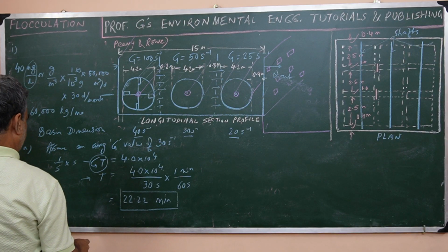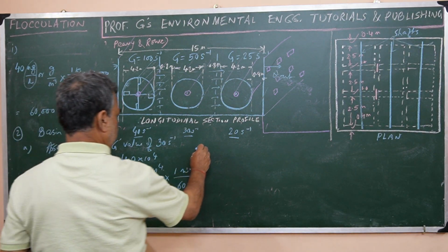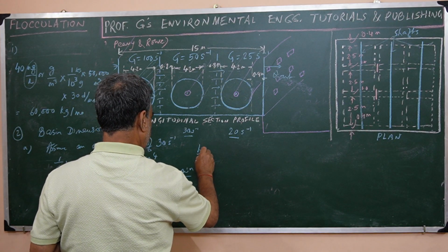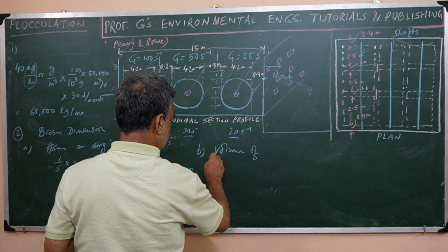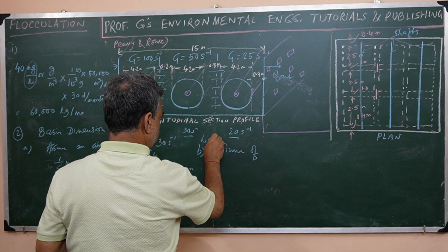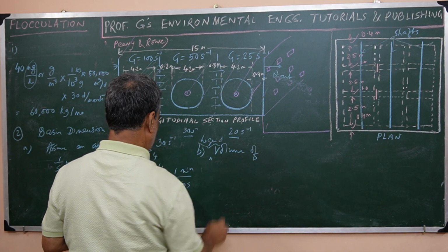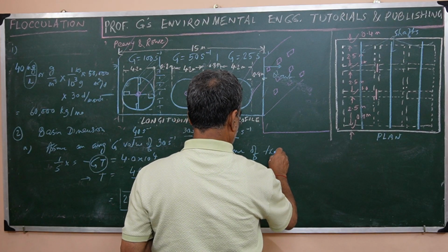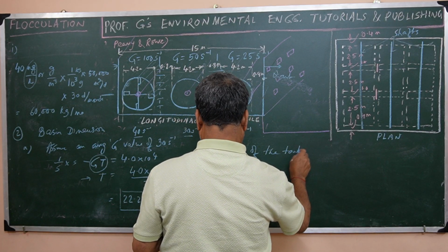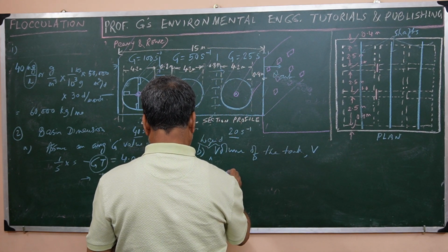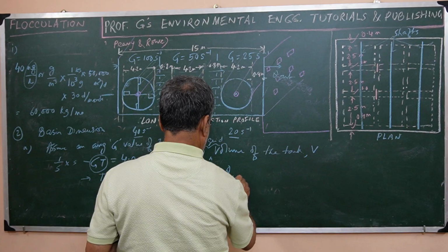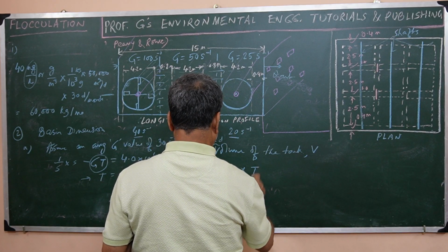So the volume of the tank will be, the liquid volume of course, that is the liquid or wet volume of the tank. So that will be V is equal to Q design into detention period.